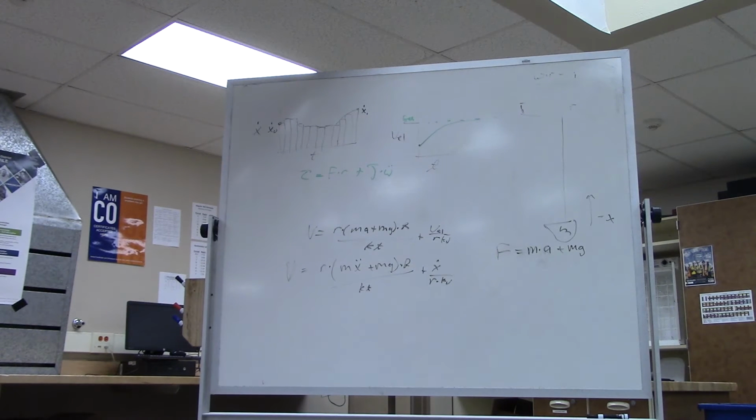So I have a question. Is there a rule of thumb for loss due to friction on chains, belts, things like that? I have found in FIRST you can ignore it for your models, because it's just so small. For gear stages, like in a gearbox, I typically attribute 5 to 10% mechanical losses.